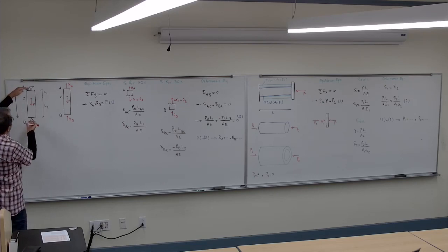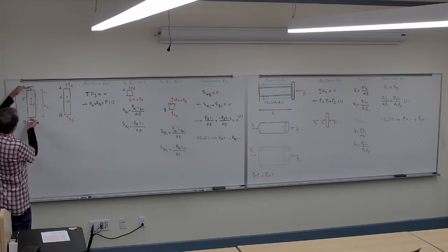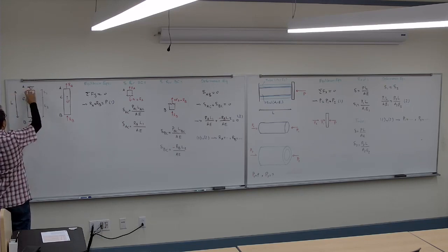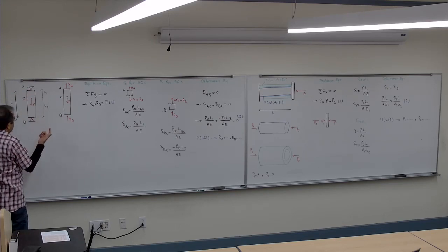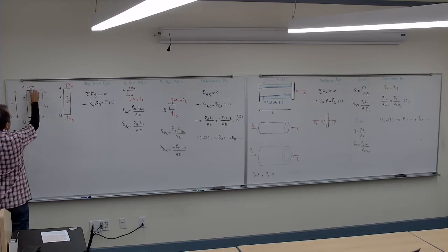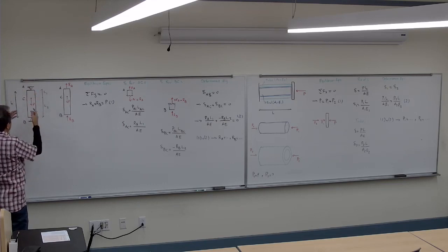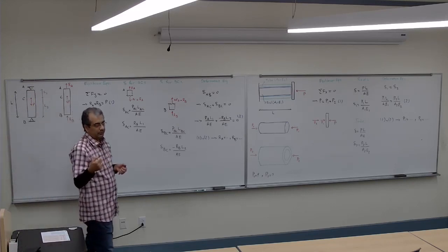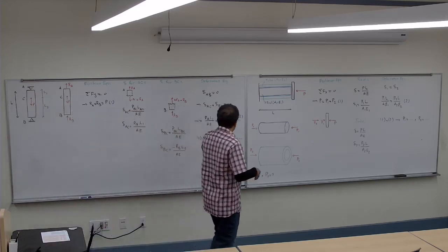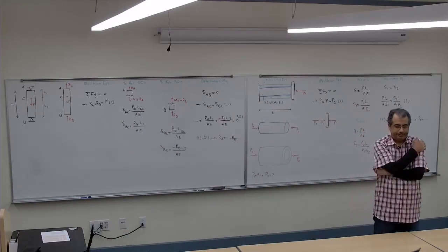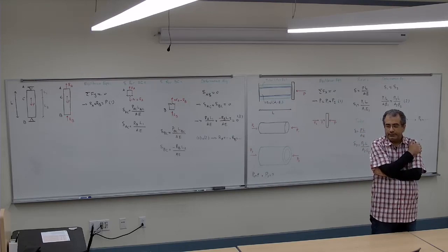Look at here. We know that the AB is fixed, so the total change in the AB should be 0, but the change in the AC is not 0, the change in the BC is not 0 either, but the total is 0. So we find the change for the AC, find the change for the BC, and said, okay, if I add these two together, it should become 0, so it gives us the deformation equation, and the second equation we can use to solve the problem. Question?